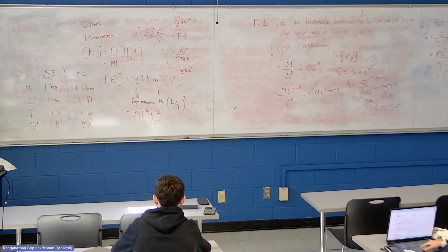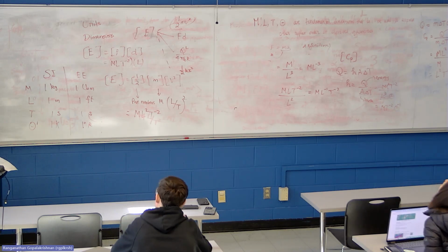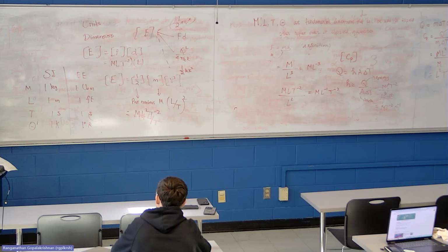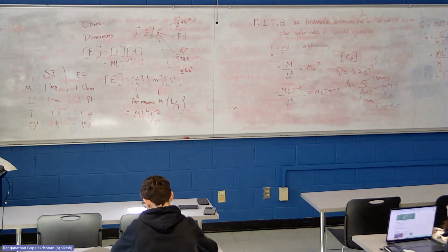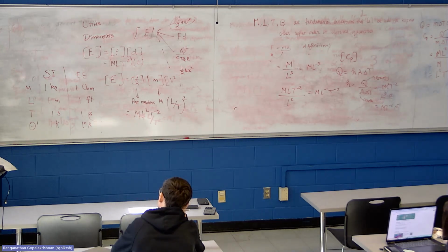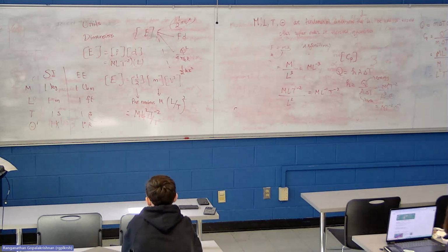Do you know what is the densest liquid that we know under atmospheric pressure conditions? Mercury. Any guesses on the density value relative to water, like X times bigger than water? Yes, 5. Okay. It's actually 13.6 times bigger. That's why we use it in barometers, because to measure a pressure difference using mercury, the height difference will be manageable in millimeters or centimeters. If you build the same barometer with water, guess how tall that column needs to be? Exactly 13.6 times taller, because to produce the same pressure difference, the height has to be 13.6 times bigger.